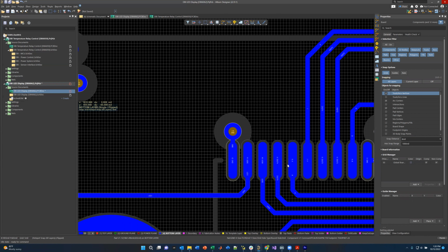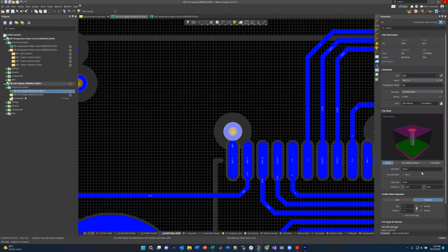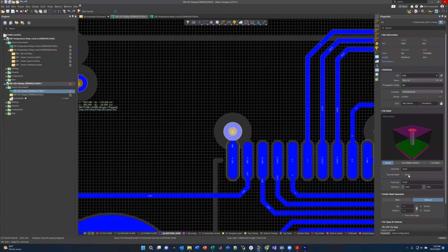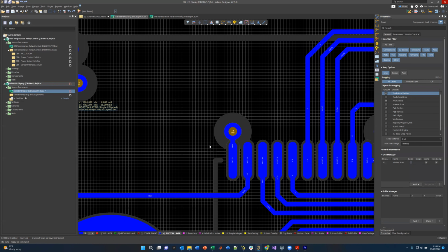So that's copper. In this case, this is a 30 mil pad, and this can be different sizes. I can make this 90, it doesn't matter. Of course, it shorts everything out. So it's a 30 mil pad for the circle, but the hole is a 15 mil hole. There's a drill, it drills the hole, and then they plate the barrel of the hole, so it actually has copper down the entire side. The advantage of that is it goes through the board, and any inner layer can connect to the via.